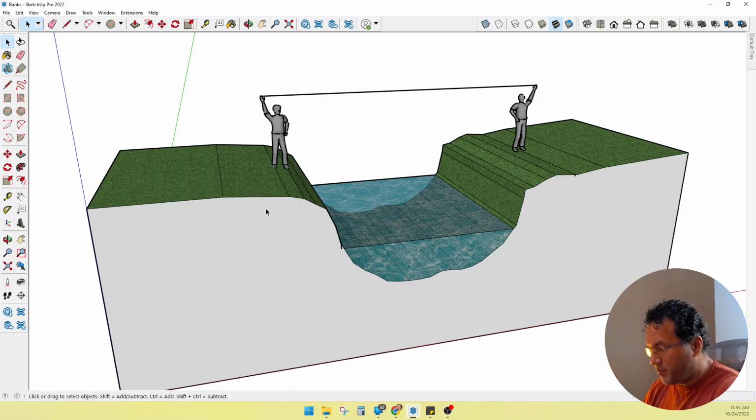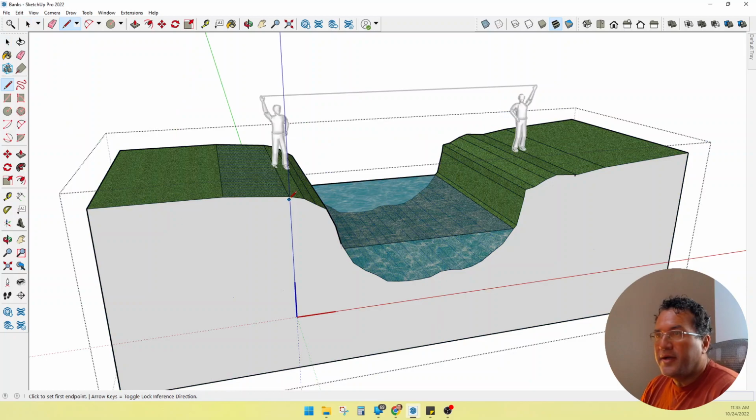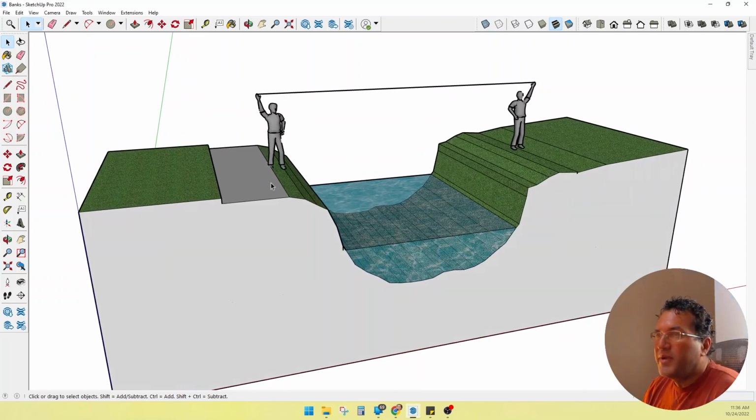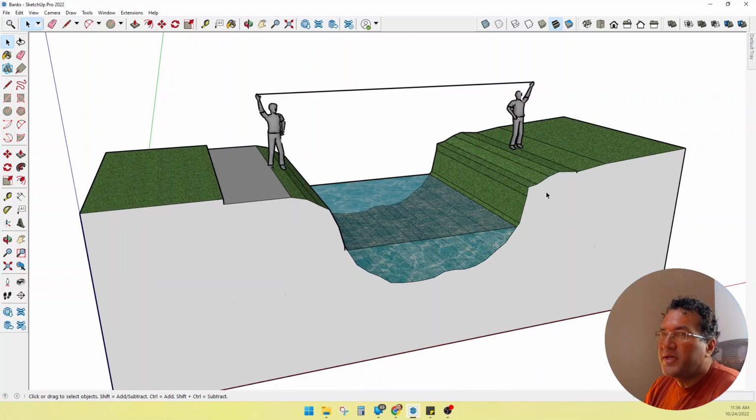So regardless of abutment, first thing you need to do is level off wherever you're going to build. And I'm not going to talk about where to build in this video. I'm just going to talk about the basic styles of abutment. Okay, so we have to get a nice flat surface. Now, elevation from bank to bank doesn't have to be completely level. One bank can be high, other bank can be low, or vice versa, and that doesn't really matter so much. Okay, so we get a nice flat surface, and if you do gravel, you just over excavate maybe a foot or two in this area here.